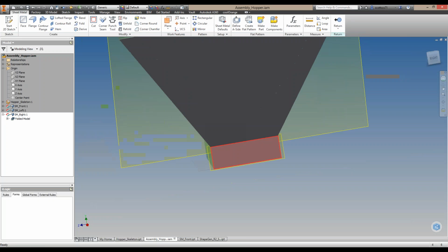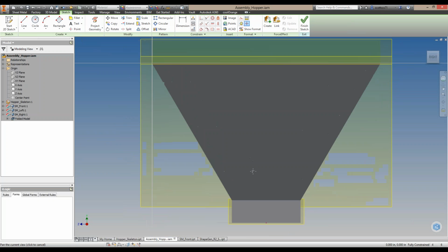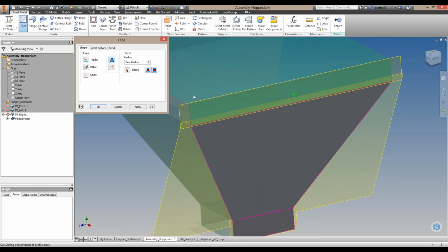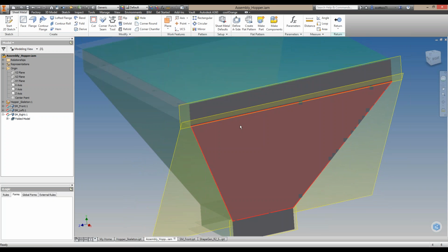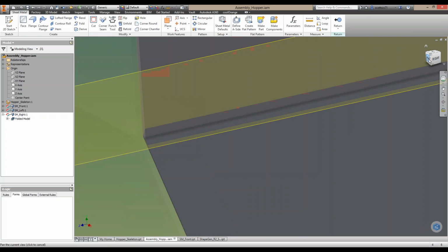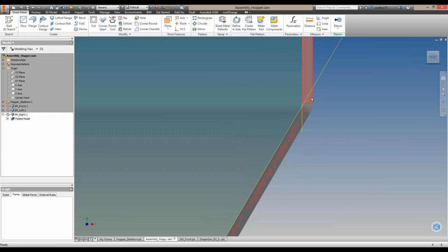And so we're ready to finish it up with the third face here. So again, 3 steps. Create a sketch. We pick the face. Step 2 is project the geometry. Step 3 is create a face. It finds the closed loop. We hit OK, and then there is the bend on that one as well. So if we want to look at this from the side, you can see there's our material. There's our sheet metal part.